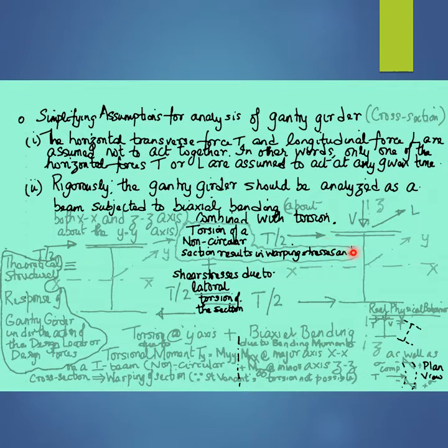And also undergoes bending about the minor axis ZZ of the girder as depicted in this figure, due to the transverse dynamic force T acting in the transverse x direction with reference to the coordinate axis illustrated in this figure as well as the schematic diagram for the industrial building structure in which the overhead electric crane is installed in one of the earlier slides.